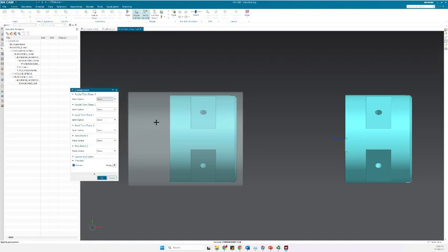Now we could define a distance, for example, but just to practice something else, I can put trim plane 1, but instead of having a distance, I can define a point to be specific on this one. But I could also define the plane distance.